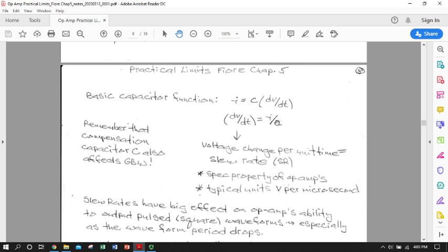If we think about this capacitor being somewhere inside our op-amp and the op-amp having some kind of current signal going through it, we could do some measurements maybe, or do some calculations on the op-amp circuit, or model it, and then find the maximum dV/dt that op-amp could carry based on the maximum current that flows through it and the size of that compensation capacitor, or the maximum current that can flow through that portion of the circuit.